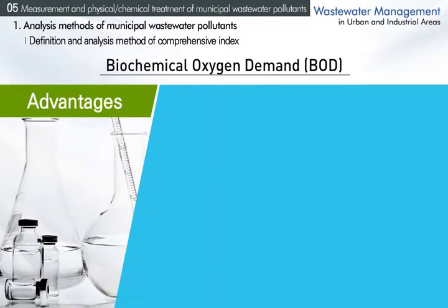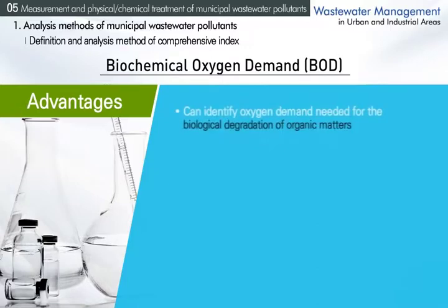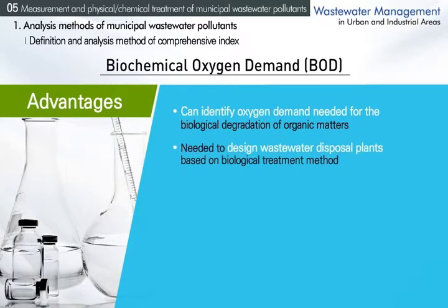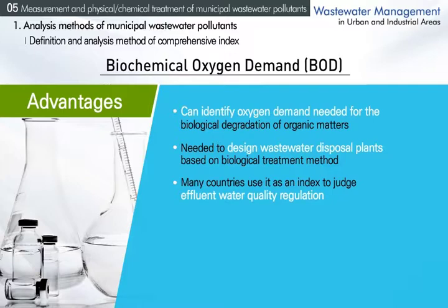Despite these limitations, the biochemical BOD measurement result tells the oxygen demand needed for the biological degradation of organic matters. So it is necessary for the design of a wastewater disposal plant that is based on biological treatment methods. Also, many countries still use the BOD method as an index to judge whether the water quality of effluent after wastewater disposal satisfies the legal regulation. So it is very important to understand and learn the meaning and measurement method of BOD well.